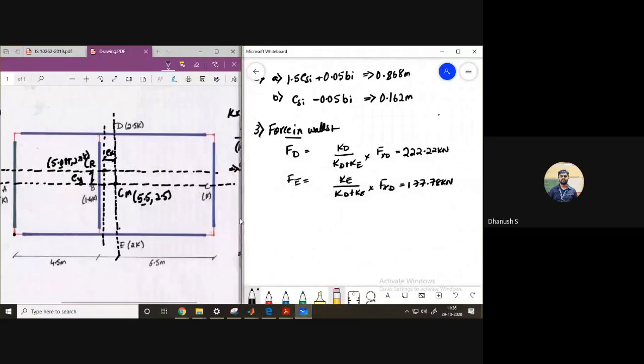Now what is the next step? Lateral force due to torsional moment. Before that, we need to find the R values. What sign convention do we follow for R values? Upwards is positive, rightwards is positive, so downwards and leftwards will be negative. We'll follow the same convention now.